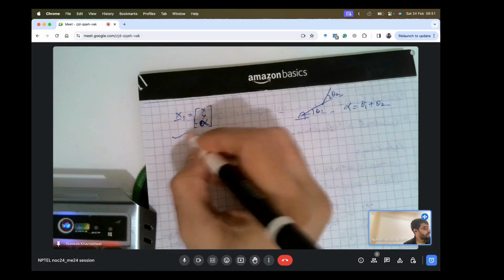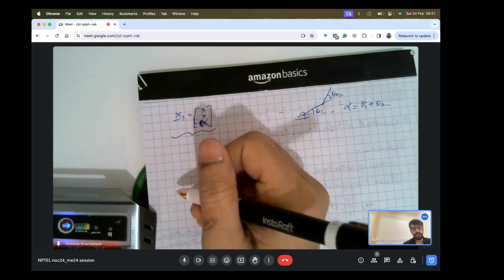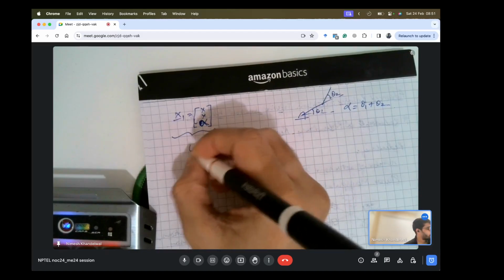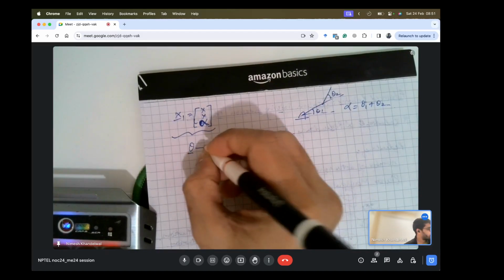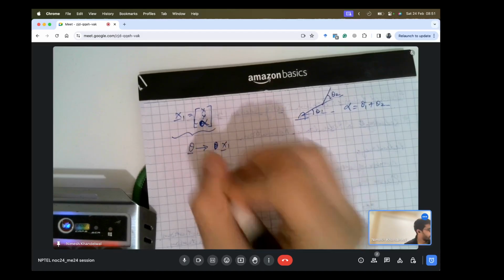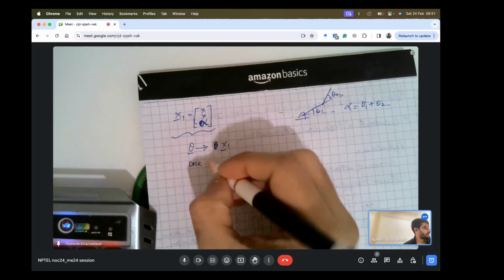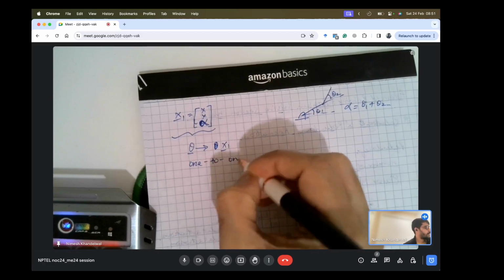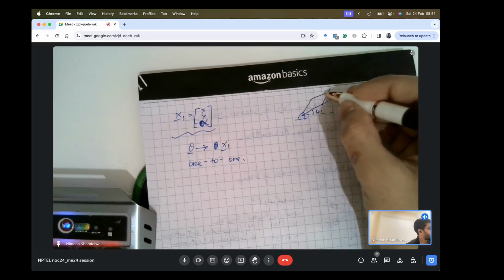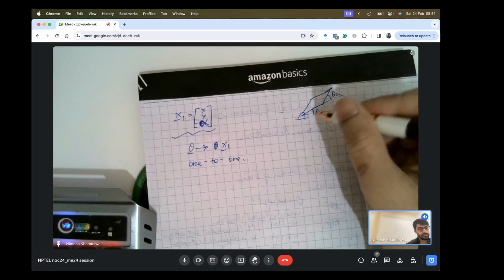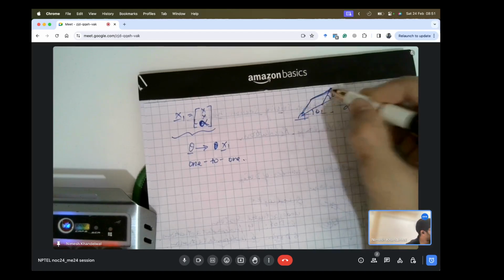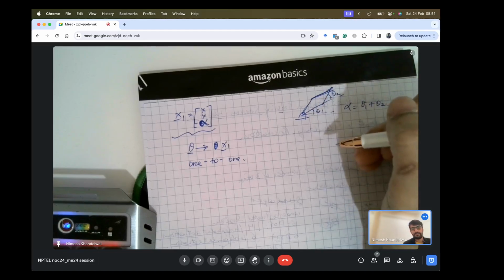Now, if we define this as the task or the mapping, the mapping from theta to x1 is indeed one to one. Even when you take the other branch to reach the same end effector position, the angle alpha is different here.